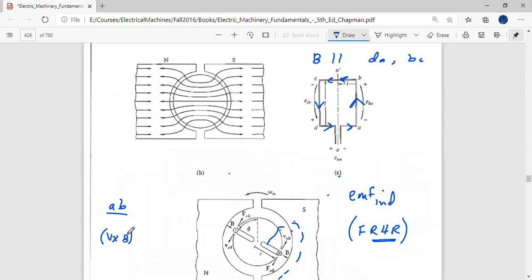So we again take the right hand rule, first finger in the direction of the velocity, second finger in the direction of the field, and thumb is pointing inwards. Okay, so the resultant of V cross B is inwards, and the direction of L is also taken as the direction of the current, which is also inwards.